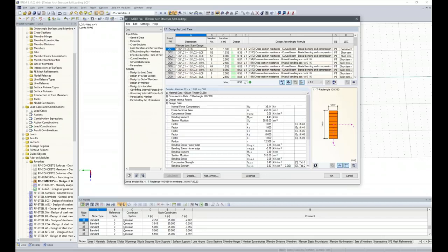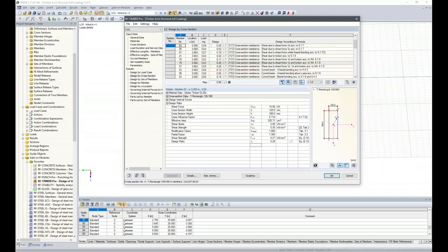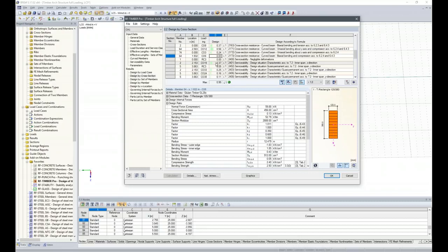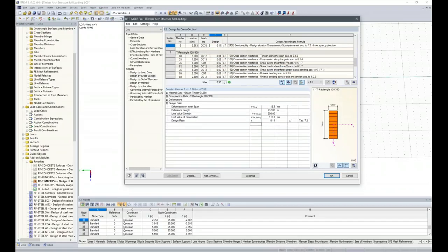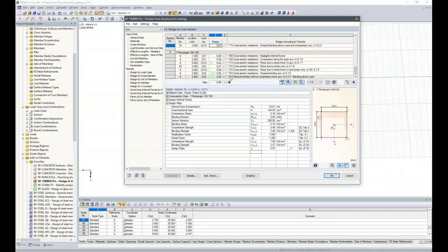So let's have a look at the design ratios now. Cross section is best. So I've increased the height of this rectangle, so it's gone a little down, the usage, from 86 to 83%. Serviceability is at 37%, so that's not a problem. And for the columns, we are now at 95%, which is a pretty good usage. Okay,